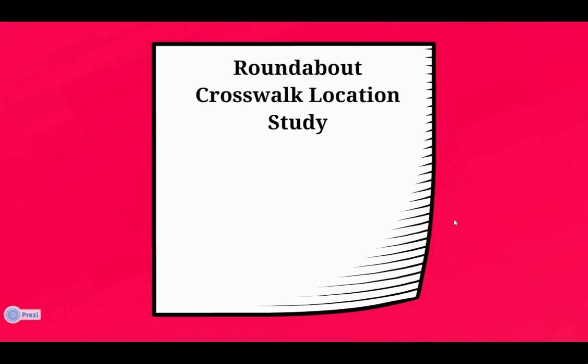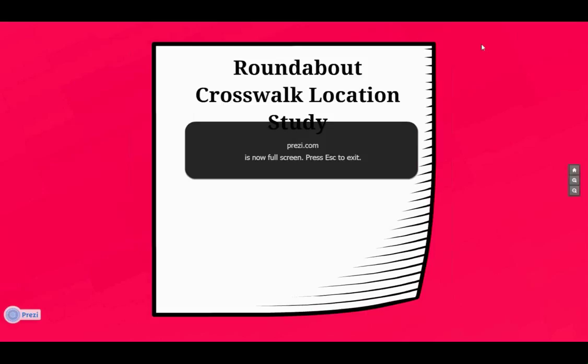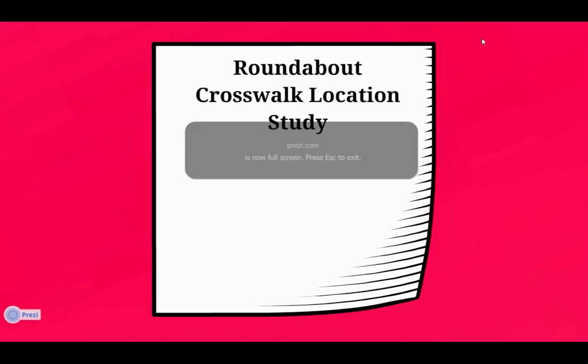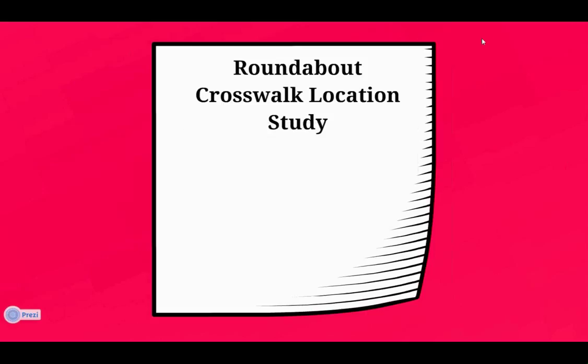So after going through many different retaining wall asset management programs, I was able to identify 6 main components that were included in each asset management program that would be included in our program as well. The first is a wall acceptance criteria. Which walls are included in the inventory system? Some agencies used the criteria of if it's 2 meters high, it's in, and if it's not 2 meters high, it's not in the system. Other agencies, such as the National Park Service, had qualifications for these walls, which included historical background and other such information.